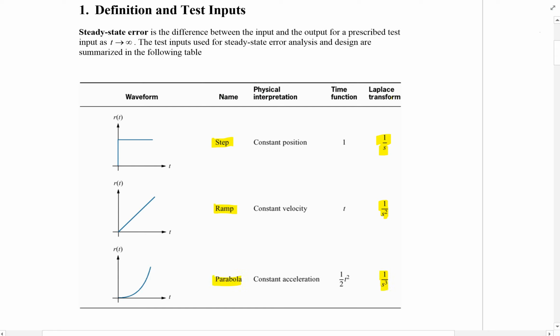For example, an oven, a commercial oven for industrial processes, you might want to ramp up to a certain temperature, maintain a steady state value, and then ramp down. Cooling it or heating it at a certain rate and then cooling it at a certain rate is very important, so that you don't destroy the part. And so ramp is a big deal.